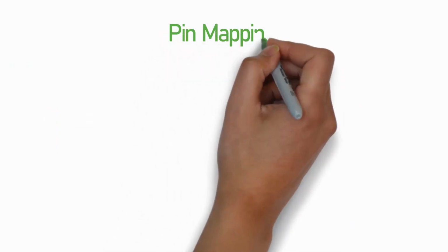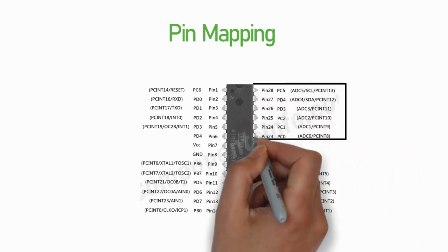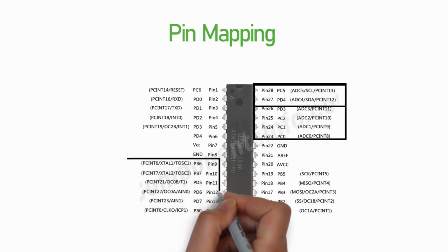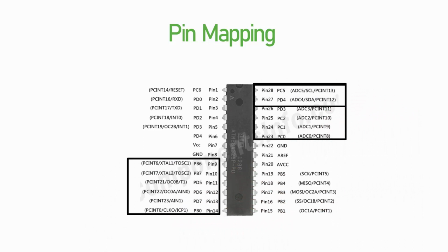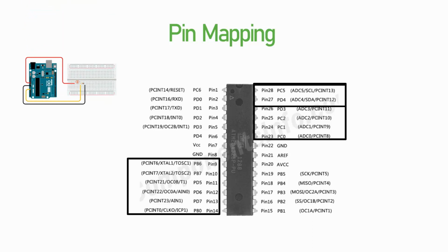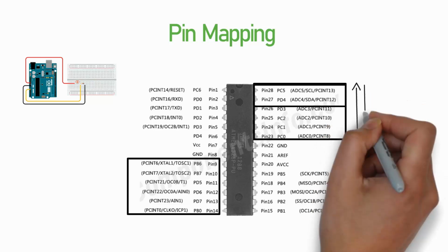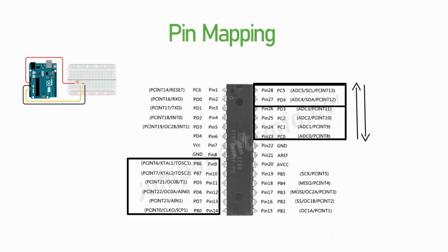Pin mapping. These days, each microcontroller's pin can be used for different features like ADC, I2C, interrupt, etc. It would be best to map each pin to the correct peripherals before starting the schematic. For instance, if you want to connect the sensor to the ADC pins, you have many different options to connect them from ADC0 to ADC5. But if you connect something to ADC5, you cannot use the I2C feature of this controller anymore. Getting this step right, including all of your desired features, helps make a more accurate schematic, which will save you the headache of having to recreate the design more than once.